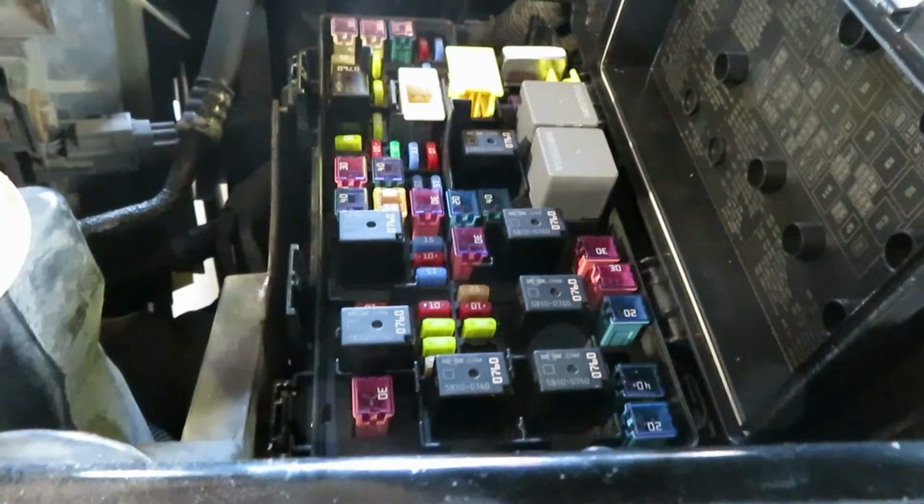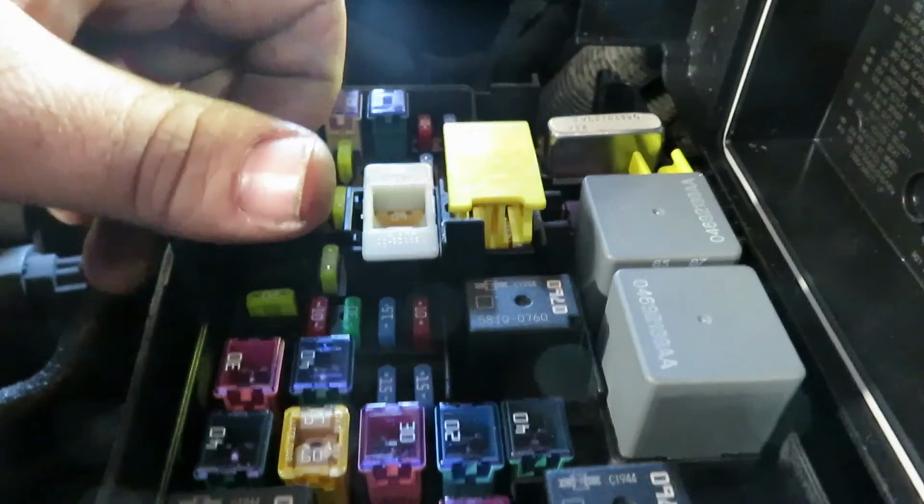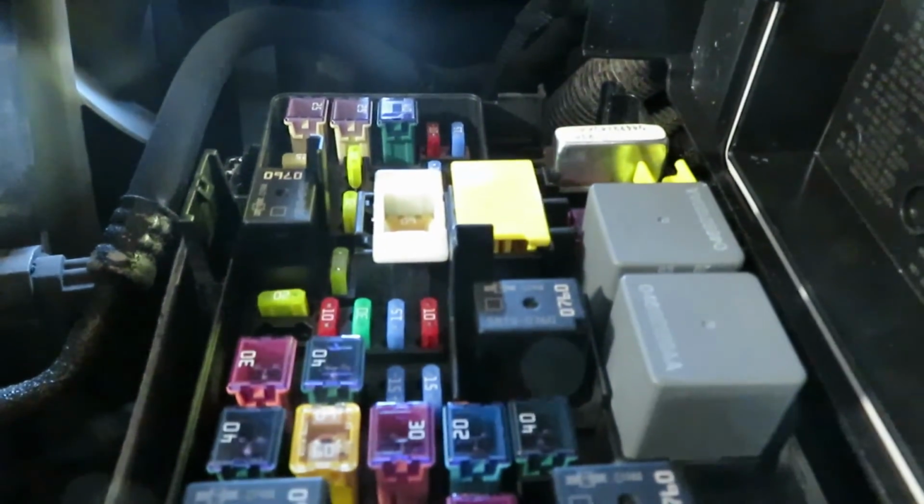So there we go. She's down inside there. Everything's all buttoned up. Power wire's back on. Now when you buy these, they come with the airbag fuses up, so it kind of deactivates the system. So all you do to activate it again, push those down, and you are good to go.